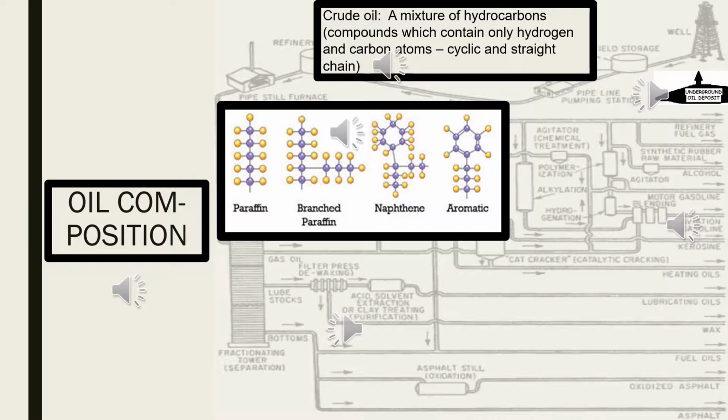Crude oils are mainly characterized by the type of hydrocarbon compound that is most prevalent in them. For example, paraffins, naphthenes, and aromatics. Paraffins are the most common hydrocarbons in crude oil. Certain liquid paraffins are the major constituent of gasoline, petrol, and are therefore highly valued. Naphthenes are an important part of oil liquid refinery products, but they also form some of the heavy asphalt-like residues of refinery processes. Also, aromatics generally constitute only a small percentage of most crudes, the most common of which is benzene, a popular building block in the petrochemical industry.